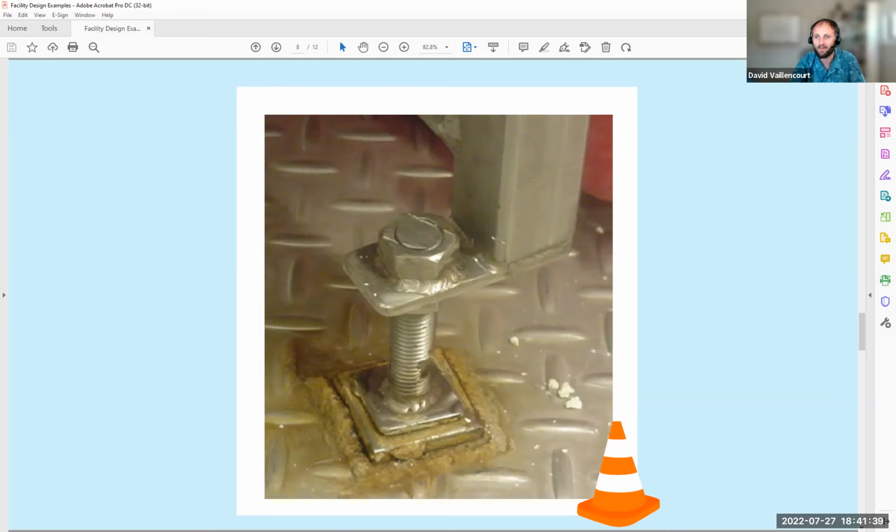Brian, did you have anything to add? Well, I don't know if you have any photographs of wall penetrations, but this is a floor joint, and similar things happen when, let's say it's an extraction lab and you need to bring piped ethanol into the room. How is that wall penetration sealed? Is it a proper gasket and a flexible escutcheon plate so that the hose can move and doesn't rip the sealant out?